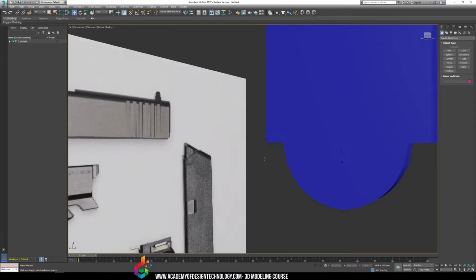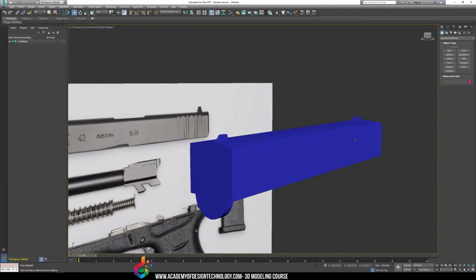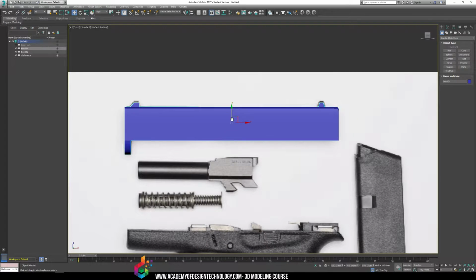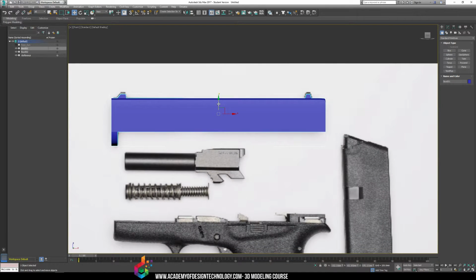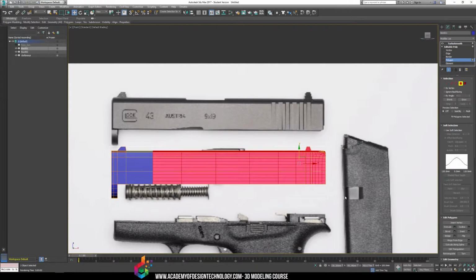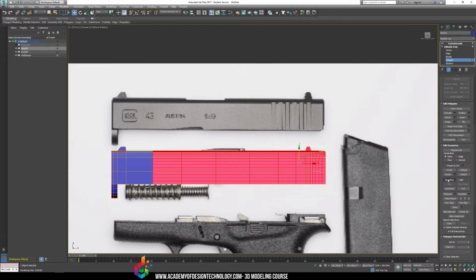Yeah, so it's just taking it slowly and steady. Like for instance, if you wanted to create these ridges on the side, I know most of you are thinking about that. What I like to do is normally I'll pull away the model for a second, and then I'll look at these ridges. I'll go to my actual model that I'm working on, and I'll slice plane where I need to across the side to match the location of those ridges I'm going to make. Remember, don't forget that we have the angle snap tool up here. If you click that and then start rotating, it rotates by 5 degrees every time. I turn it off because I have the right rotation.